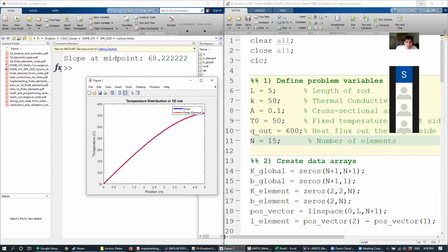Dr. Chen, is there any thought process behind the ends that you're choosing? Or do you just usually go like 2, 4, 6, 15? Yeah, that's a great question. When you do a mesh convergence test, you want to definitely start gradually. You don't want to increase it too much because you might miss some interesting behavior. But you can just have a feel for it.